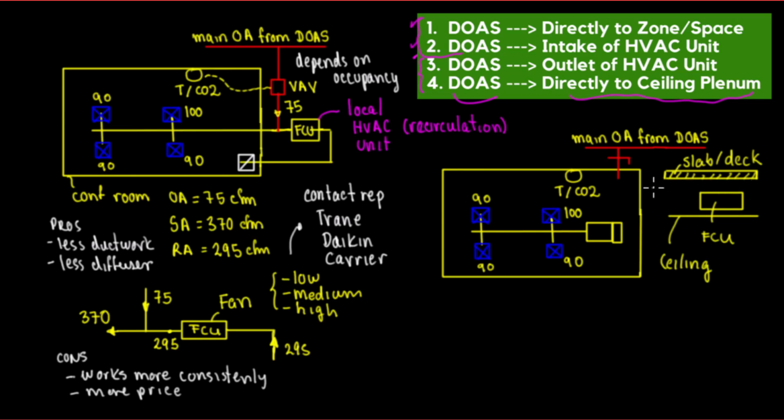This is ceiling, okay, ceiling plenum, which is very important to coordinate with the architect early in the design, because usually I ask for maybe 20 inches plus at least. Sometimes the architect wants to give me 14 inches, 15 inches. So it's very good to be open, being honest at the beginning, because I've seen projects in the beginning like, hey, I'm gonna give you 14 inches. Oh, and then after that, we'll figure it out. But then after that, it's too late because we're on another, remember the design phases, right?